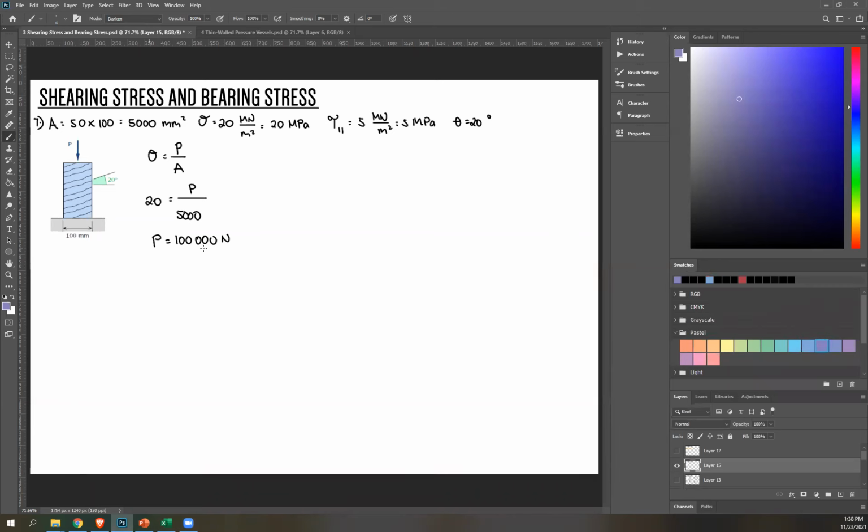Now, that's not just regular shear stress. As you can see, it's mentioned that that's shear stress parallel to the grain. So we can just use V over A, that's V over inclined A. Now, luckily for us, we've already derived the equation for that, right? And that's shear stress parallel to the incline, P over 2A, sine 2 theta.